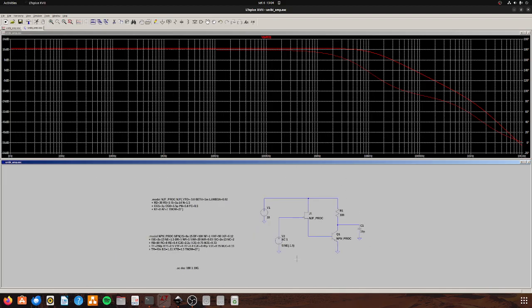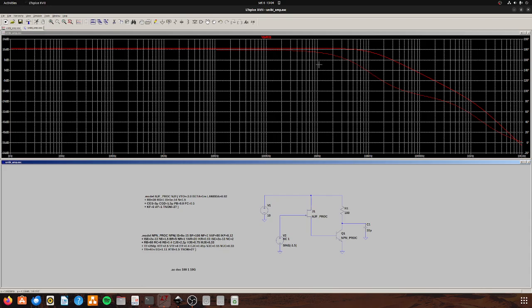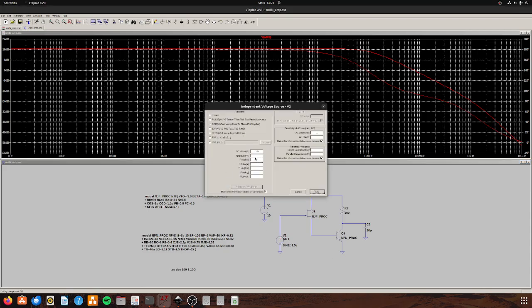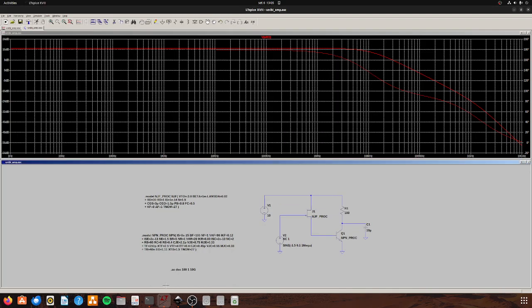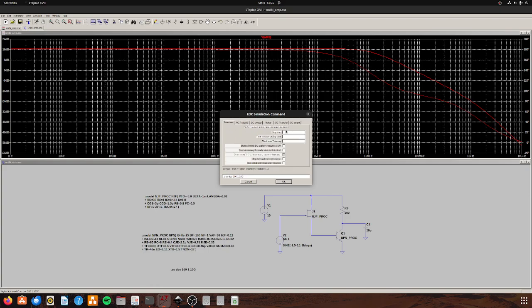So if you want to amplify an AC signal, I will check diff 1 mega. So I will write here 1 amplitude. I will put like 0.10, and I will set the frequency to 1 mega, just so we can check distortion, and we'll change this to transient. Start then. I have 1 mega, so I want 5 views, and maximum time step I will want 100 pico. Wait, stop time must be positive. Stop time. Oh, okay. Forgot.